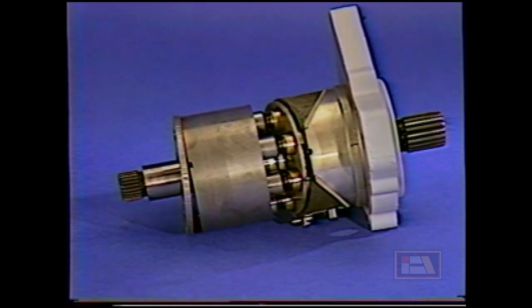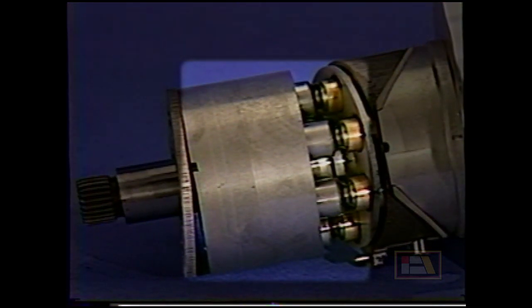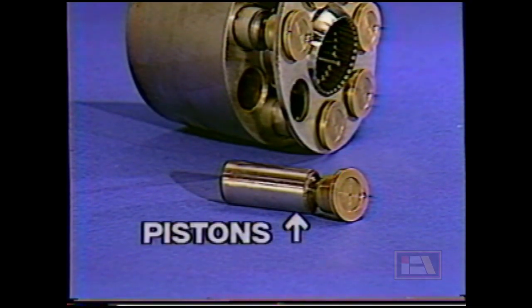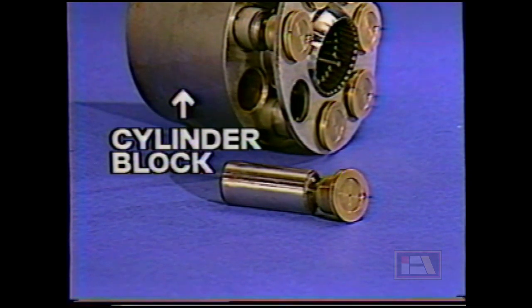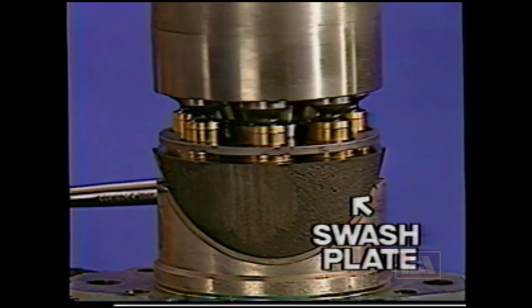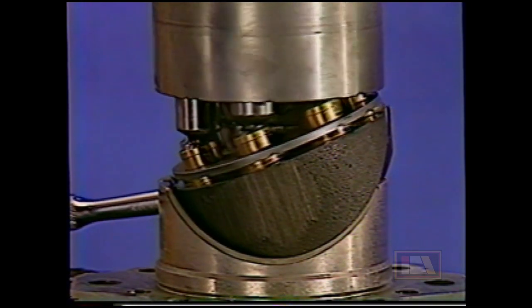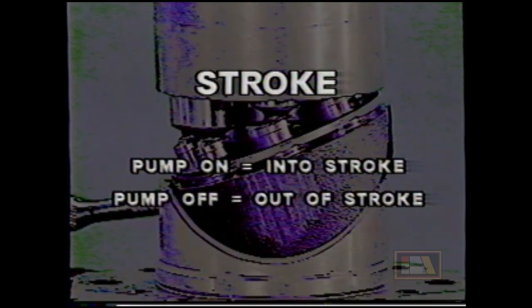Let's take a look. As you've seen, the axial piston pump contains a rotating group and a swash plate. The rotating group is made up of pistons, slippers, and a cylinder block. The swash plate is used to stroke the pistons in and out of the cylinder block, depending on its angle during rotation. By the way, the term stroke is a common term used by technicians when talking about the hydrostatic pump turning on or off. You can say the pump goes into stroke, or the pump comes out of stroke.